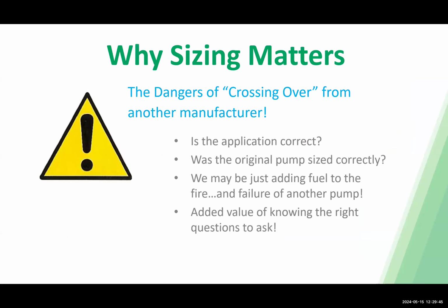So continuing on why sizing matters, the dangers of crossing over from another manufacturer. You got to ask, is the application correct? And was the original pump sized correctly? It's very possible that just because someone else has already done the sizing and everything, and you're just crossing over from their pump, it's very possible that they didn't do the sizing properly.